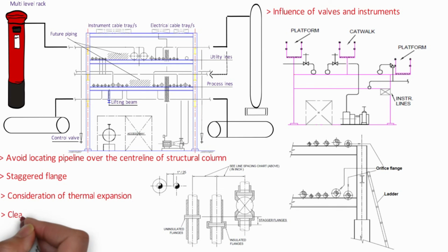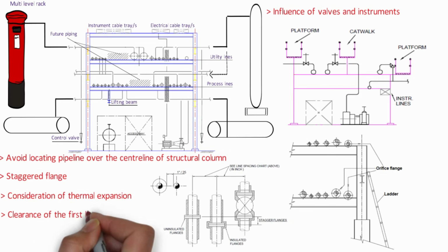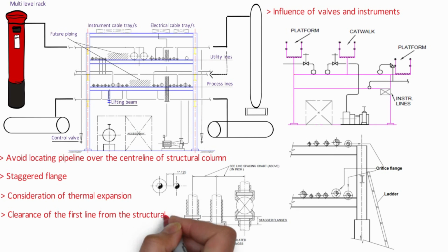The clearance of the pipe rack line from the structural pipe rack column is to be established based on the sizes furnished by the civil or structural engineer based on column arrangement in layout. After analyzing all the requirement and arrangement, the dimension to be rounded off to the next whole number.